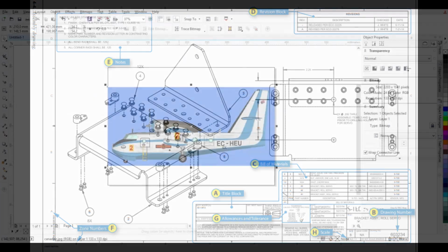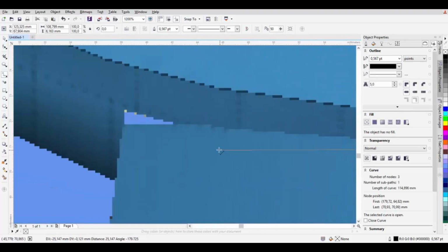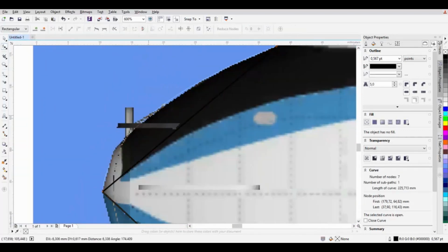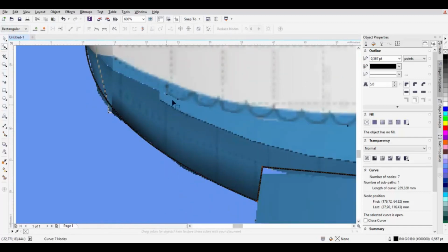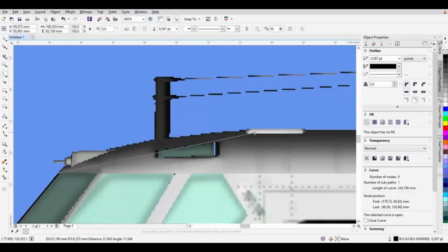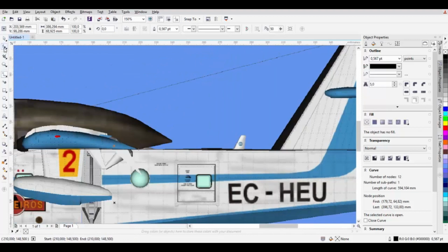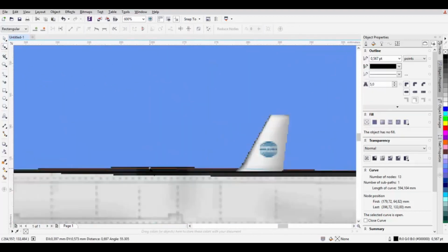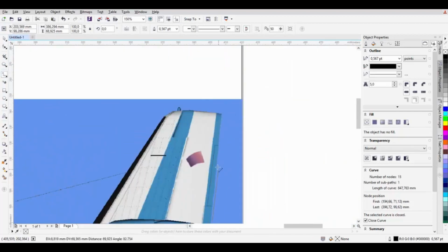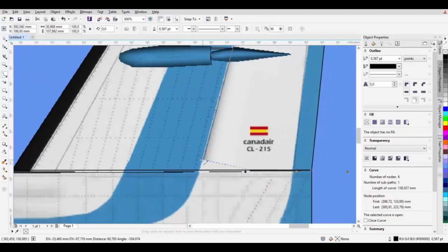Universal Numbering System. The Universal Numbering System provides a means of identifying standard drawing sizes. In the Universal Numbering System, each drawing number consists of 6 or 7 digits. The first digit is always 1, 2, 4, or 5 and indicates the size of the drawing. The number 1 indicates a drawing of 8.5 by 11, number 2 indicates an 11-inch by 17-inch drawing, number 4 represents a drawing of 17 inches by 22 inches, and 5 indicates a width of between 17 and 36 inches but on a continuous roll.